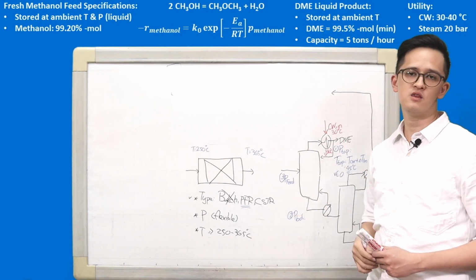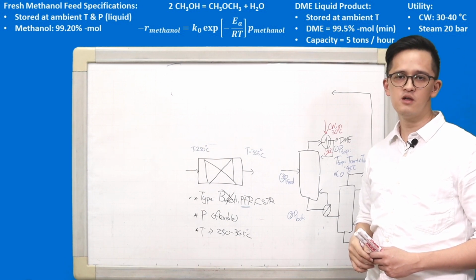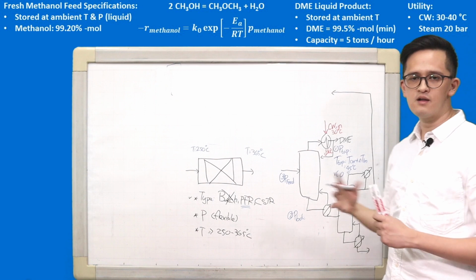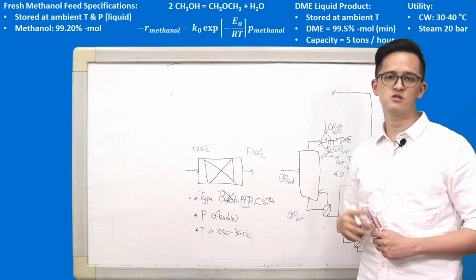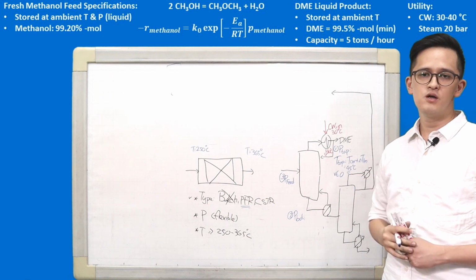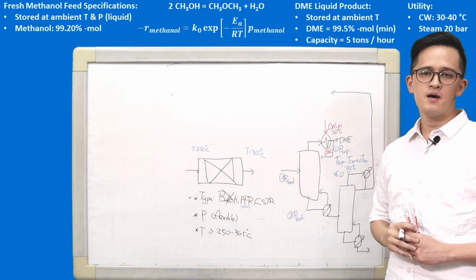We can calculate the bubble pressure. Okay, and that can be done very easily using HYSYS. So I'll switch the window now so I can help you to make the dummy stream for this product to help you getting the correct top pressure.